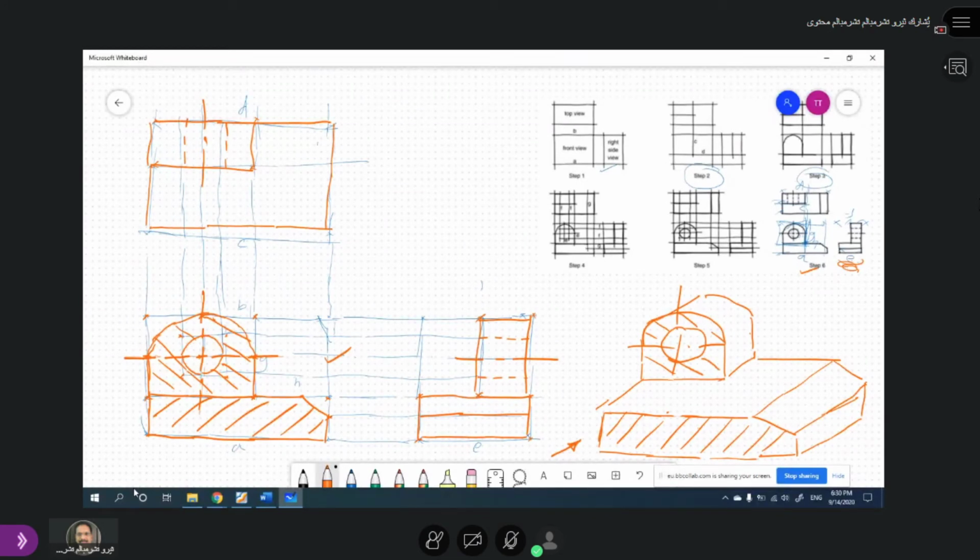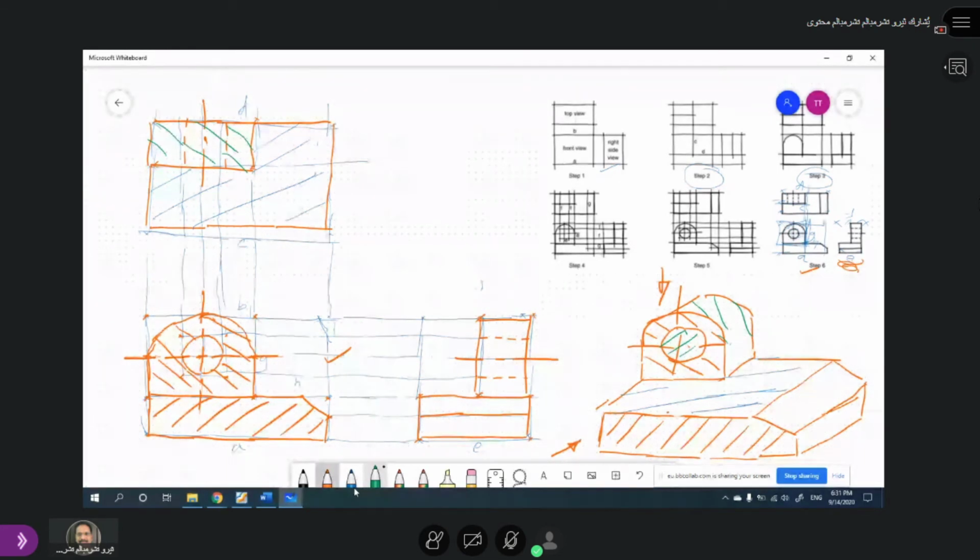Here is the circle. Then I see from the top. So this is the top view. In the top view, let's see. This is the surface I could see. Correct or not? From the top view, so here this is the surface. And also I could see this surface. So here that is the surface there, but this hole is not visible. That's why this is a hidden line. So this is the surface there, and of course I missed one thing here. What did I miss? I missed this. So what does it look like? It looks like, so that'll be, now it is okay. Correct or not?